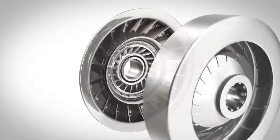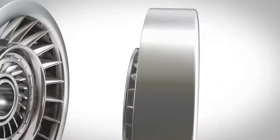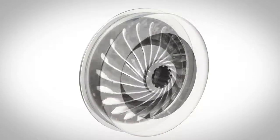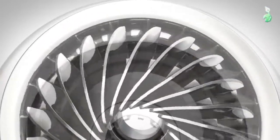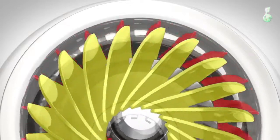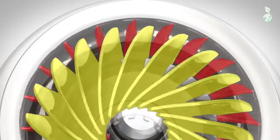The turbine is situated opposite to the impeller. In fact, you could say that the turbine is an impeller rotated by 180 degrees. The fluid flow from the impeller is directed over the blades of the turbine, so the turbine rotates. The blades colored in red are those of the impeller. The yellow ones are those of the turbine.